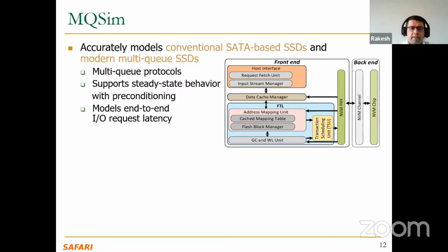By steady state, I mean the simulator can prepare the SSD to reach a state where the data cache is warmed up, and it also triggers the garbage collection process. A large amount of data is written in the preconditioning process to prepare the SSD so that the SSD performance can be evaluated in that manner.